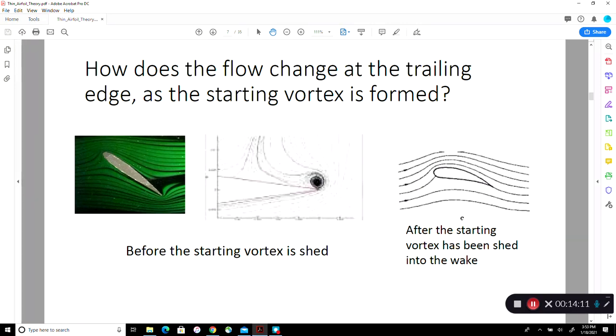So the pressure is the highest according to the Bernoulli equation. That's why when you run an airfoil code or some other fluid dynamics software, or Fluent, you'll get a very high pressure value. Here, CP, the pressure coefficient, would be almost close to 1. You don't see any other stagnation point in this case in here. Okay.